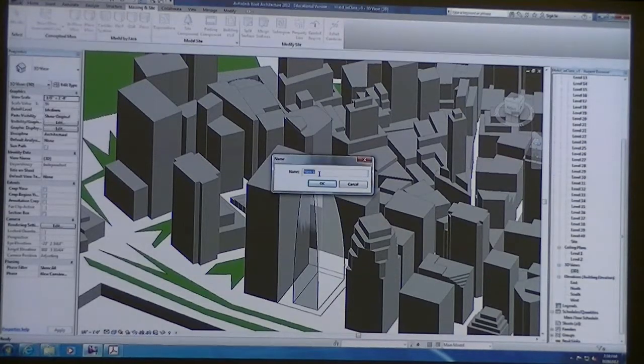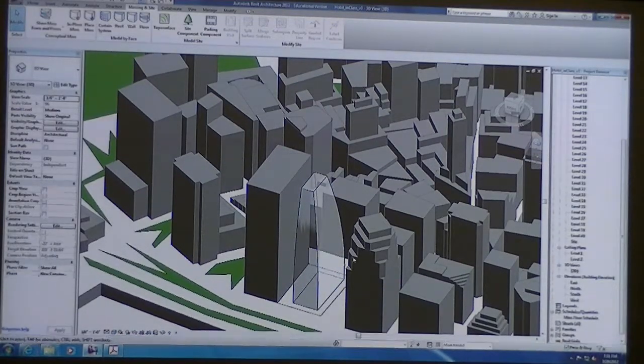And you might give it a name, something like hotel, something obvious of what you can differentiate between your zoning mass and a hotel. And you can go through kind of the same steps and start to model within this bubble. And again, you can use your voids, you can cut. You might just kind of play around with the form a little bit. You might just also check to see how big 287,000 square feet is going to be within this bubble.